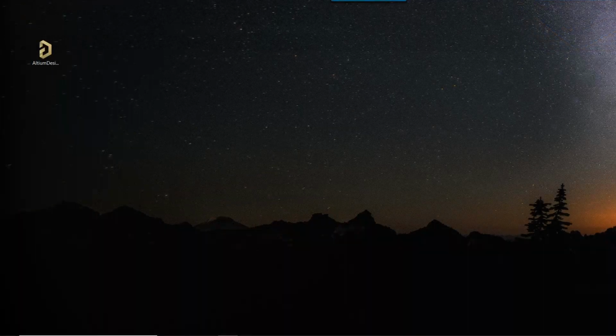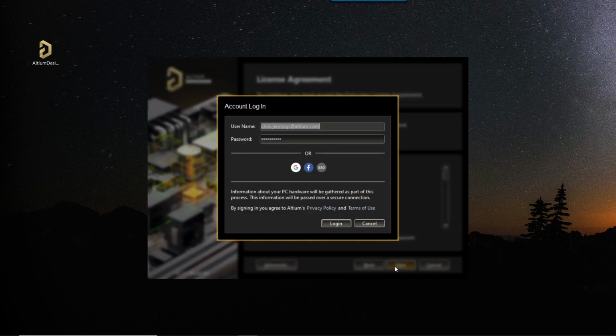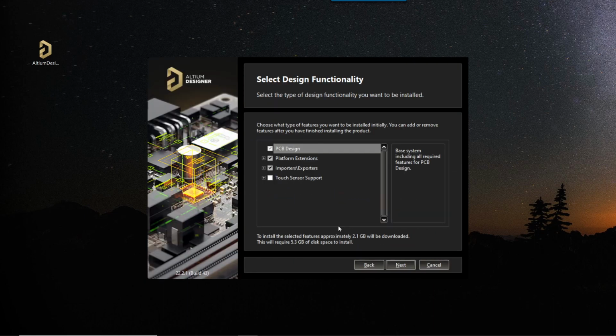Following the download link for the tools, we have the install executable now on our desktop. To start the installation, right-click on it and select Run as Administrator. Again, this is to avoid any permissions issues with the install and is recommended. The account login pop-up window is looking for your Altium Live username and password that you set up originally to kick off the process. Ensure the target folders are empty.